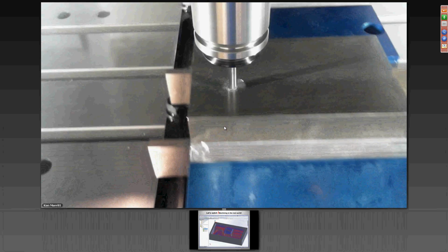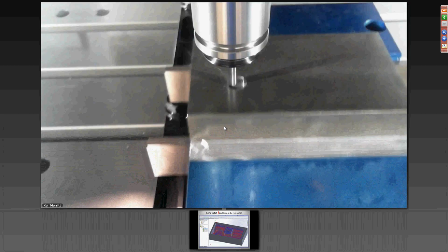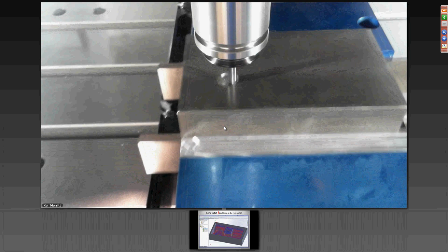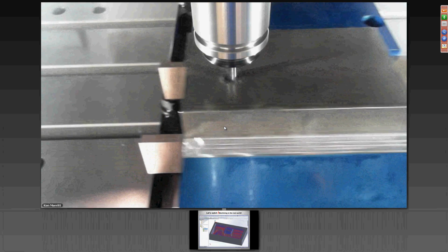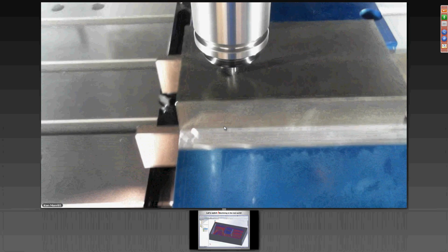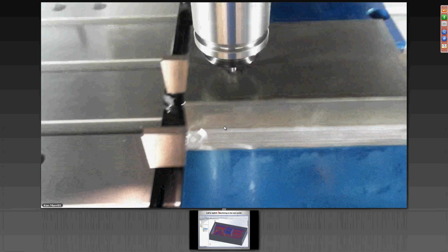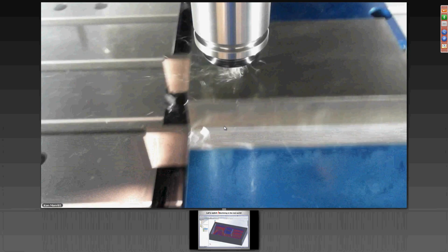All right. Now, iMachining does support pre-drill locations, so you can pop some holes in here and then come right in and start cutting. But in this presentation, I also like to show you that we can just helix right into the material. Very, very good control over the helix. We have independent control on the spindle and the feed rate for the helix versus the rest of the cut.